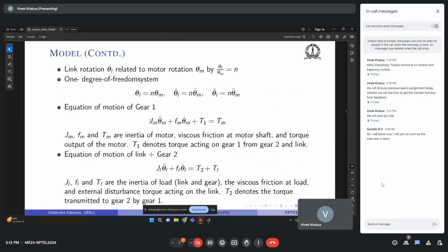This is your inverse dynamics equation, your Euler-Lagrange equation, and you can substitute it there, and you would get it in terms of the rotation of your motor. Here are the factors, that is the inertia of the motor and the friction that is there in the motor. So this is a second order system which is dependent on viscous damping.